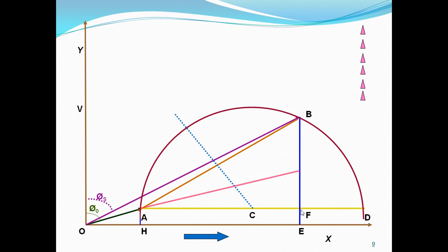At point F. Now, this line AB is called the output line, and the mark G on BF, where BF shows the rotor copper losses and stator copper losses, and H represents fixed losses, that is hysteresis and eddy current losses with a small amount of stator losses.